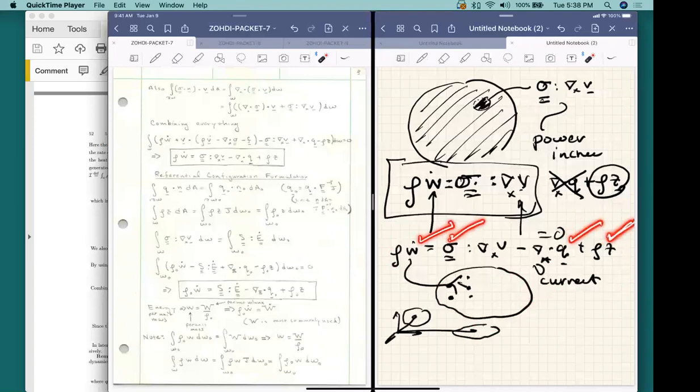For example, this could have been a battery, right? It could be a battery system where we have some mechanical separator, we've got cations and anions on one side, and the electricity is flowing back and forth through the separator. That, of course, leads to all kinds of heat buildup. That's how batteries get hot. So this equation is also the equation for batteries as well. So the heat buildup from flow of electricity through a system is also included in this kind of a system as well. So we need to keep in mind that it's a generality and we will tailor it later.